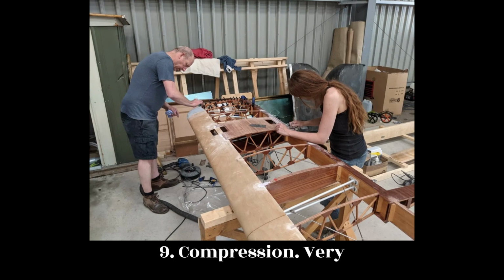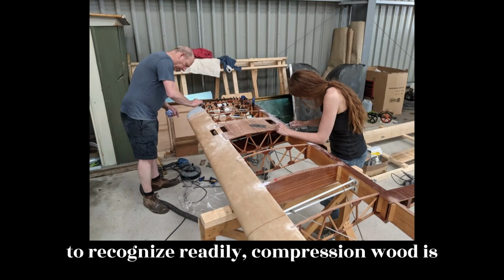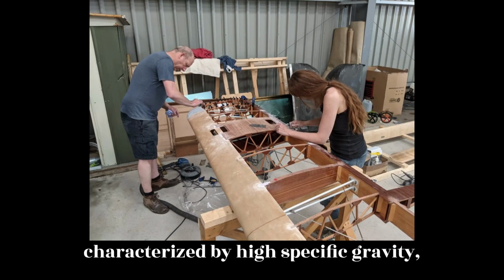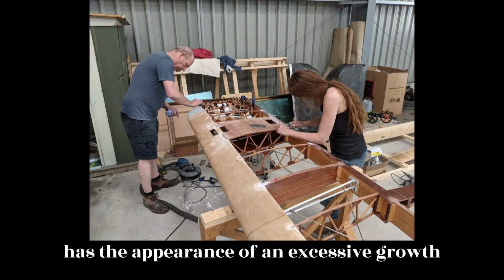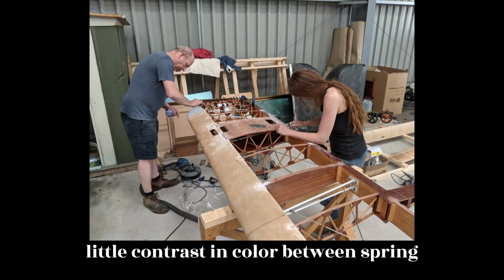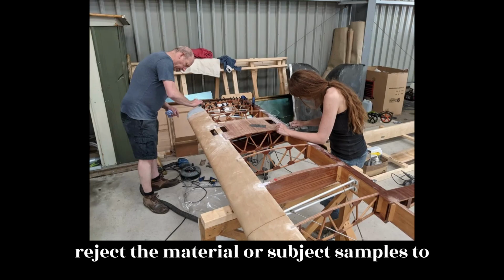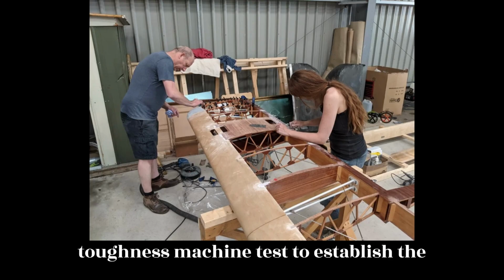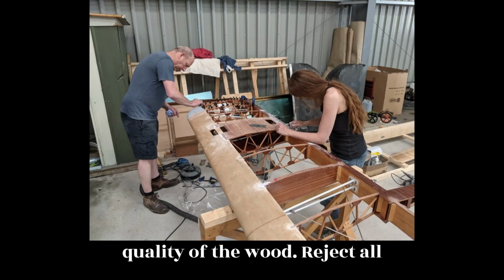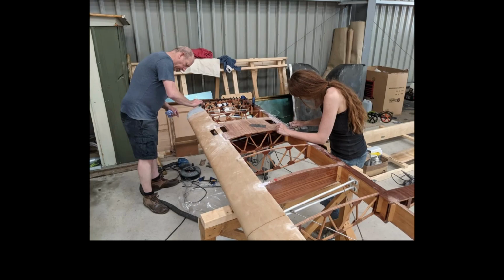9. Compression wood. Very detrimental to strength and is difficult to recognize readily. Compression wood is characterized by high specific gravity, has the appearance of an excessive growth of summer wood, and in most species shows little contrast in color between spring wood and summer wood. If in doubt, reject the material or subject samples to toughness machine test to establish the quality of the wood. Reject all material containing compression wood. End of page 6 to 8.